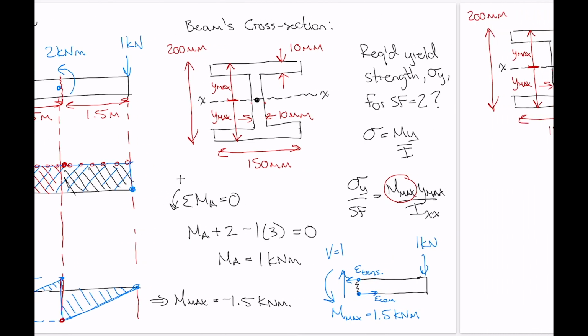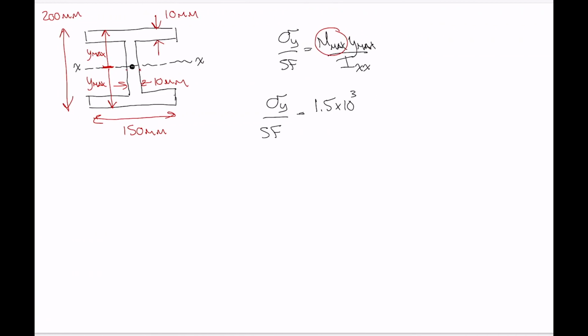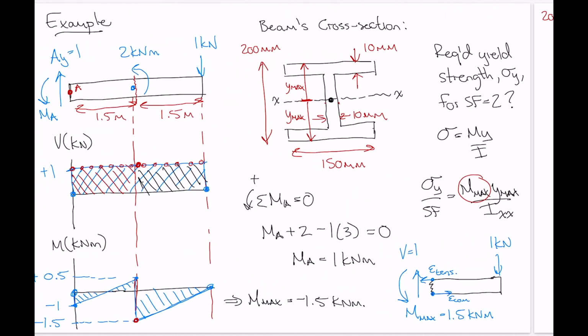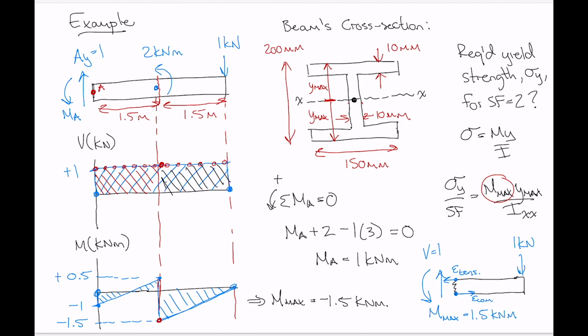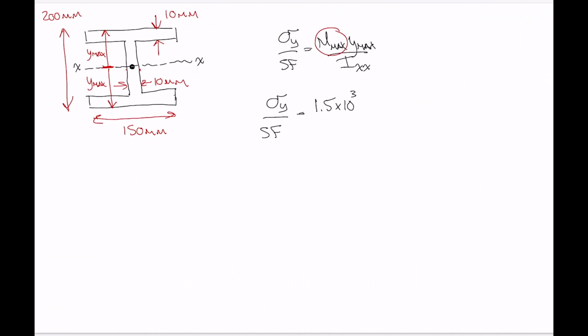But because the I-beam is symmetric with respect to the axis of bending, the value of tensile stress and compressive stress are going to be equal to one another. Okay, so if I were to take this beam and say it's projecting back that way, then our internal moment is acting about the axis in this direction, M max.